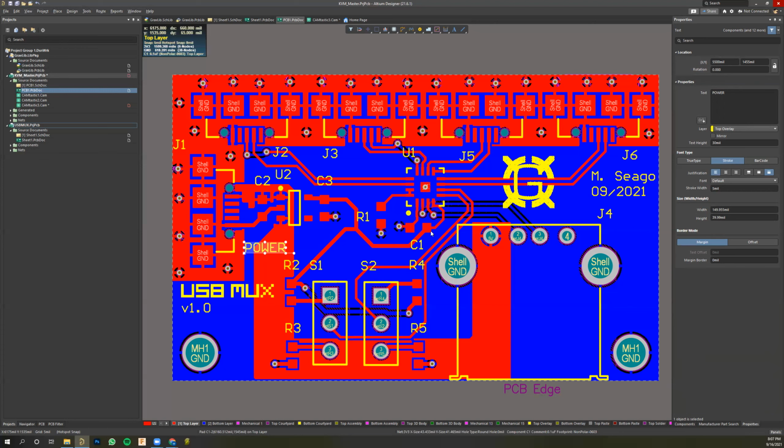And just any useful information you have. I always like to say, give your software person as much information as they can handle, and then go ask them what other information they'd like to have on the board, and what kind of pinouts they want on the board. Like if you had I2C lines, you might put a little pin header and break it out for your software guy or gal.